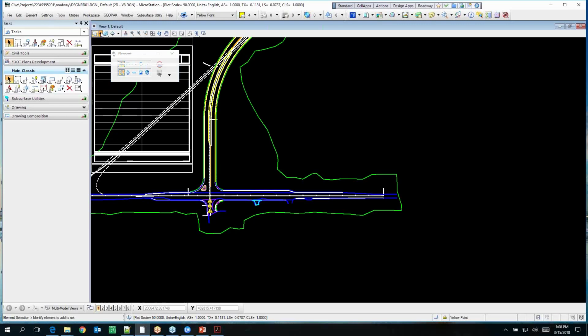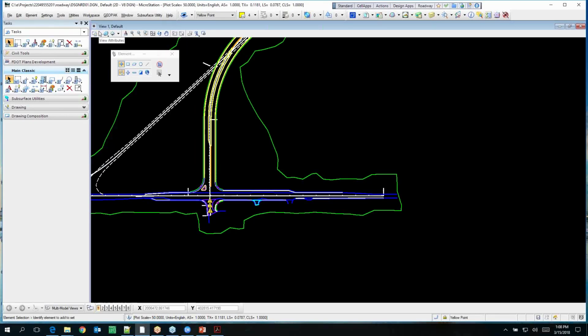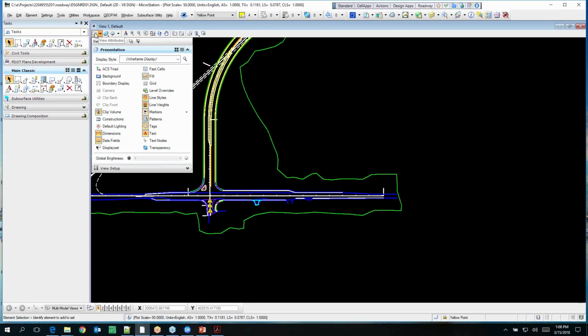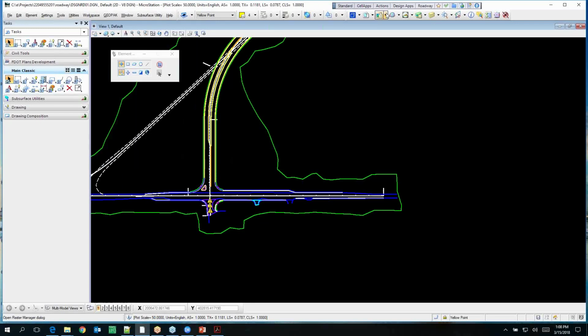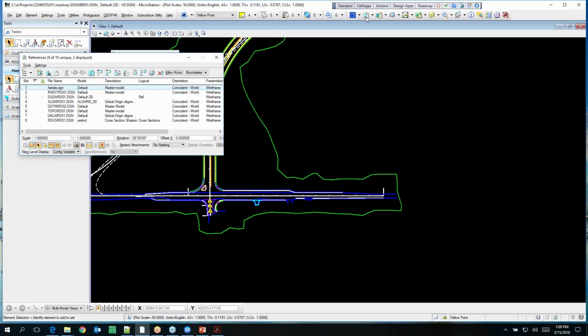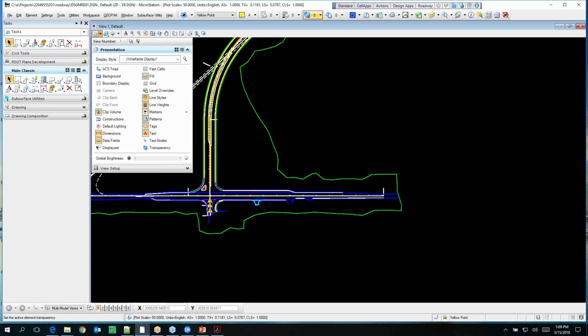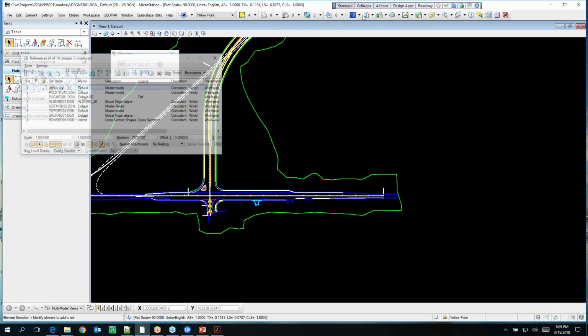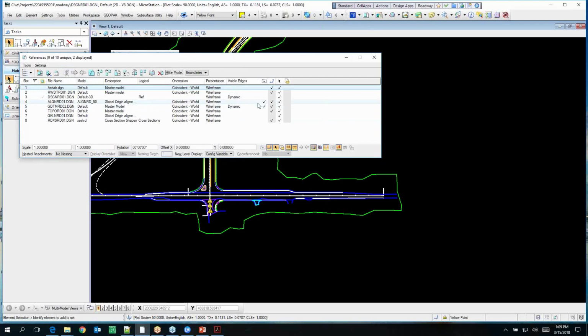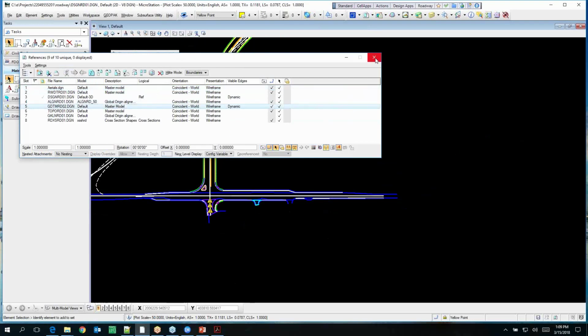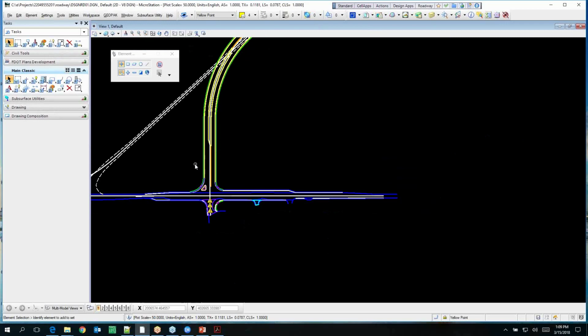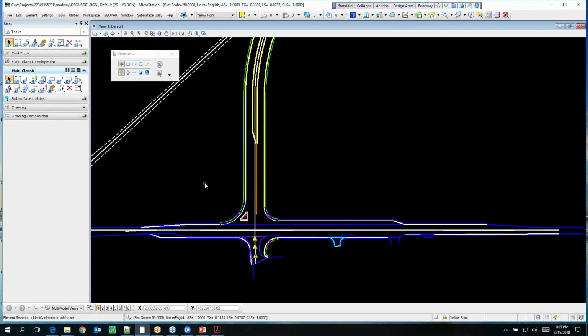So what I was trying to do was just open a single plan view. So you guys can hit Control F1 and do that. And you want to turn construction elements off. Those are already off on mine. You want to turn any references that are showing up off. Are you on 10.2 or 3? This is 10.2.